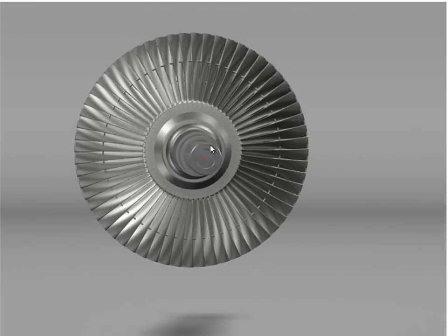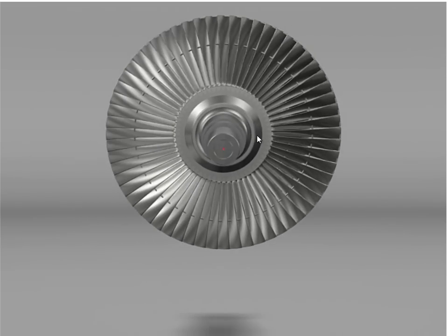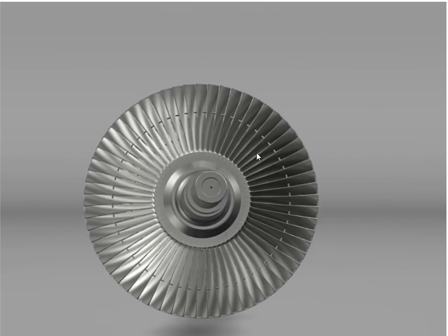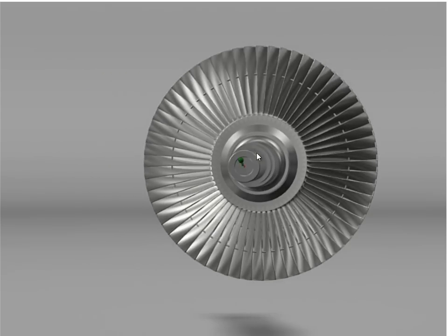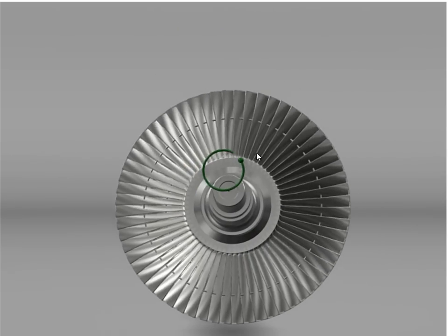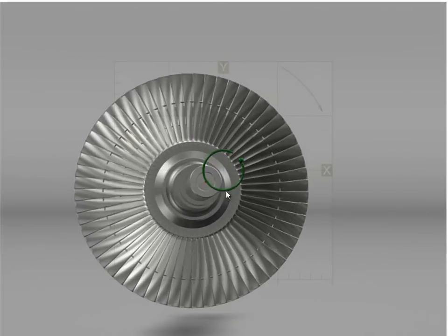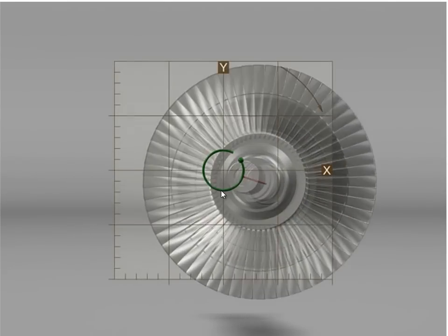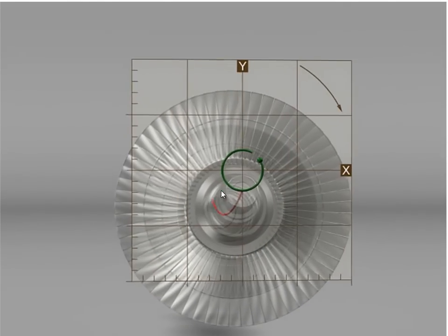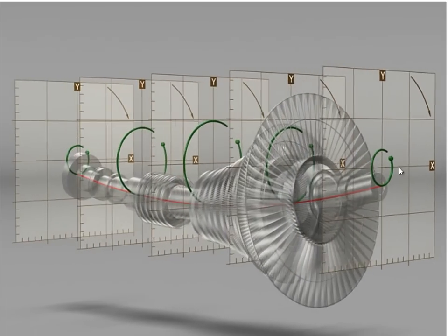that's what's going on. Well, imagine if we had our two proximity probes at 90 degrees apart, and they were taking the measurements, and we compared the two sine waves. We end up with a Lissajous figure, as it's often called, or an orbit. We plot the two sine waves against each other. We end up with a circle, if it is moving in a circular motion. And we plot that on a graph, as you can see here, y being the top, x being the side.